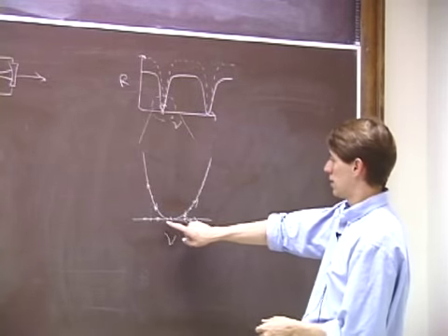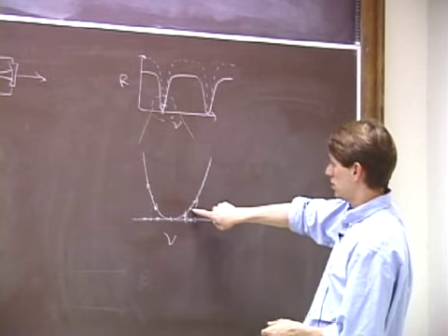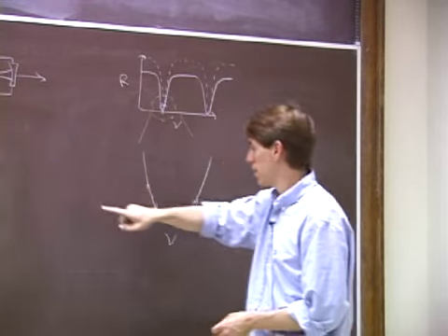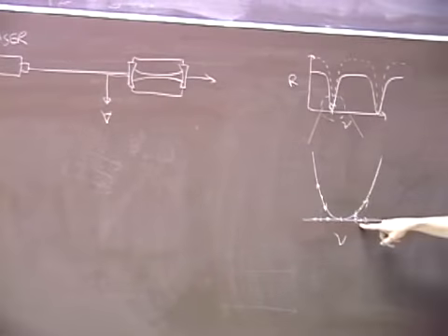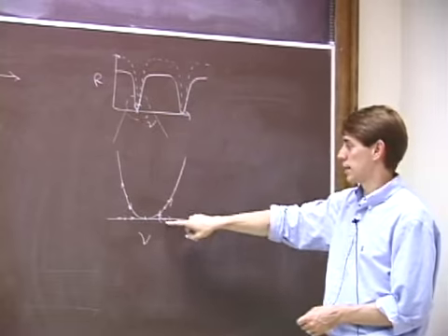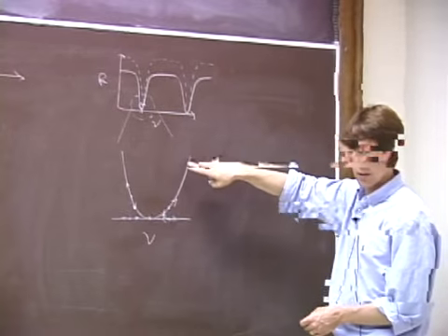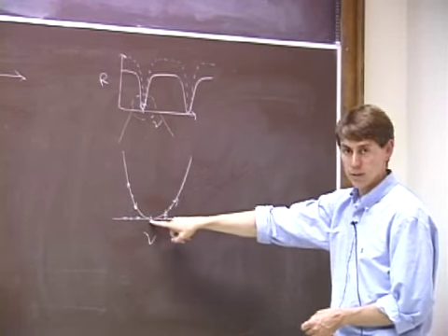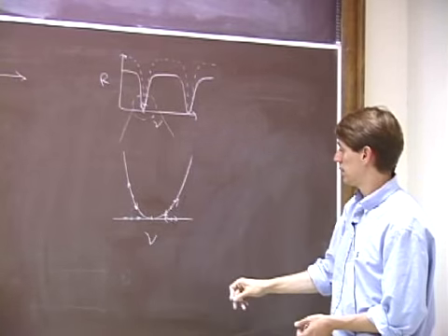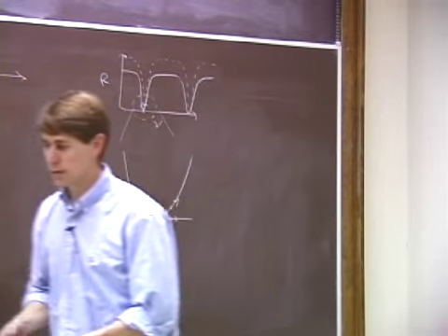And so if I can measure the output of this photodetector and compare it with the drive that I'm using to change the laser frequency in a phase-sensitive way, then I can measure the derivative of this curve, and I can tell which side of resonance I'm on. And I do this by comparing the signal. Let's see, I've got a diagram here I need to follow.